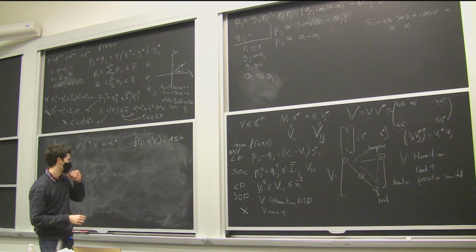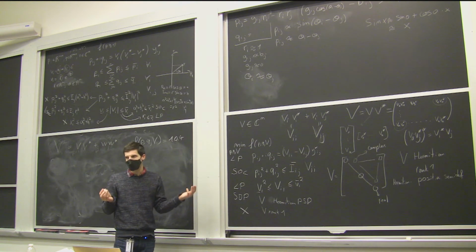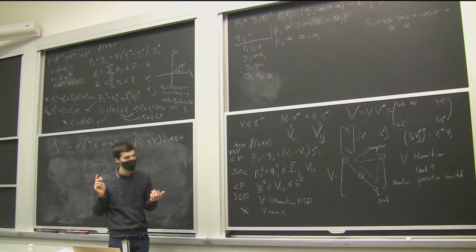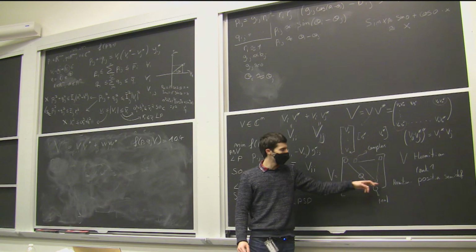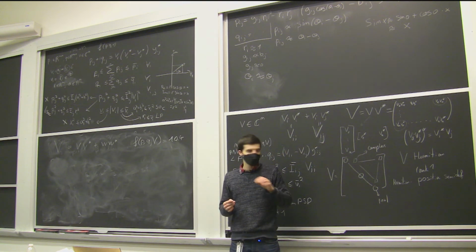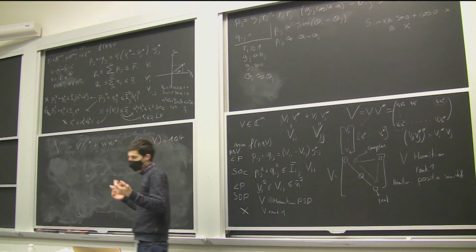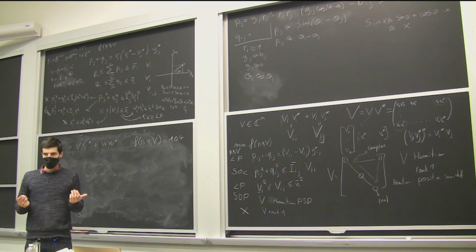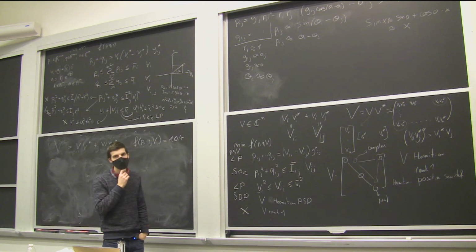Okay, so we won't have time to talk about Benders decomposition, but that's okay. Let's just finish this. So in practice, some people don't like this because even if it's a convex problem, the number of variables grows a lot. Because here, suppose you have 1,000 nodes. Then here the number of complex numbers grows quadratically. So if you have 1,000 nodes, here you have almost 500,000 numbers, sorry. So if you have millions of variables, when you solve an LP, it's okay. But if you solve an SDP with millions of variables, you will suffer very badly, okay?